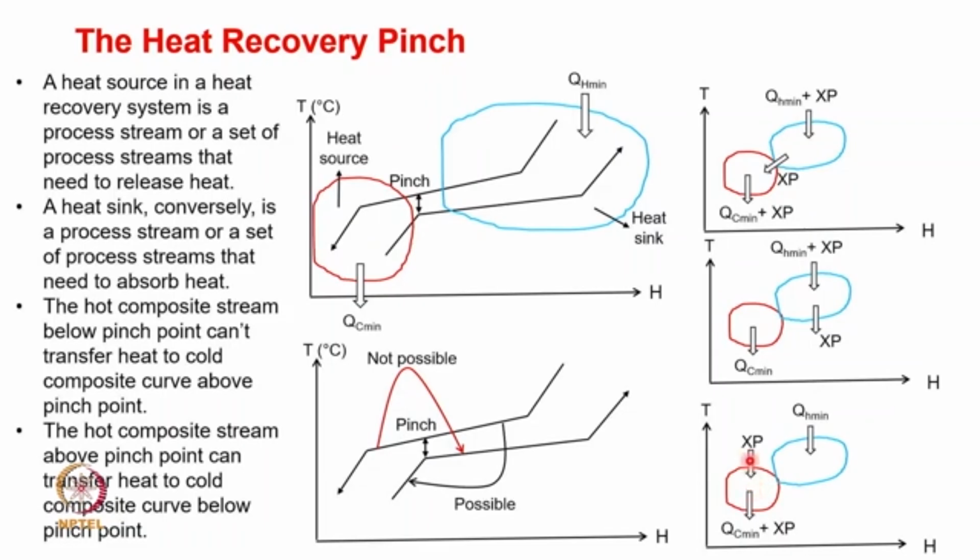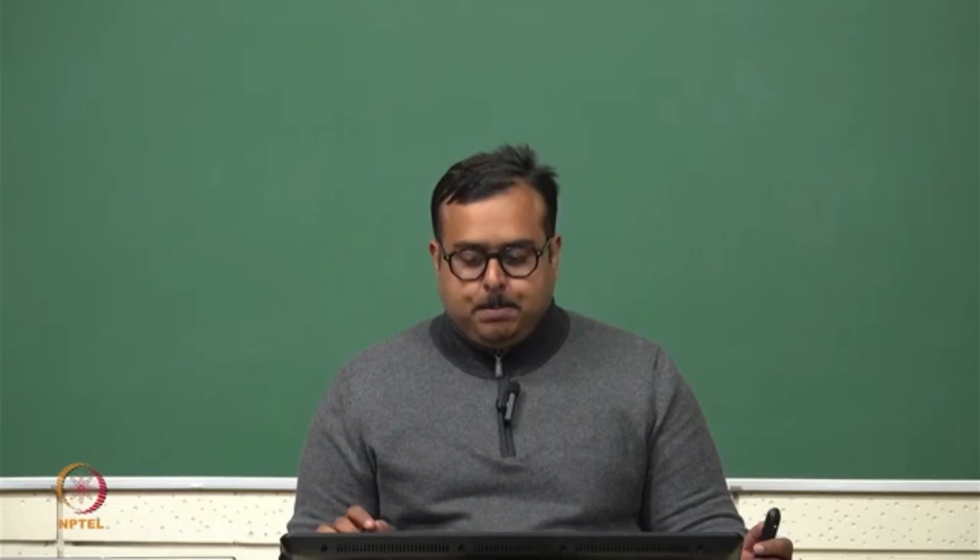And if you see, let us say you are providing the heat not in the hot stream, but in the cold stream, it would eventually come back in the cold stream. So this kind of additional heat addition is typically not recommended. Why? Because especially when you add heat in the cold stream, it would typically increase the heat of the cold stream and eventually heat transfer becomes more constrained. Okay. So a proper arrangement would require not just addition of heat, not just the removal of heat arbitrarily, but following the correct principles of heat recovery.